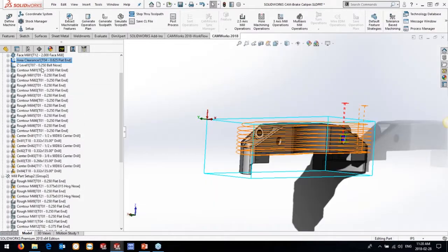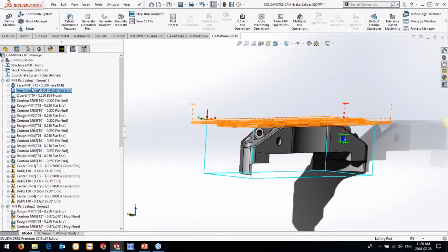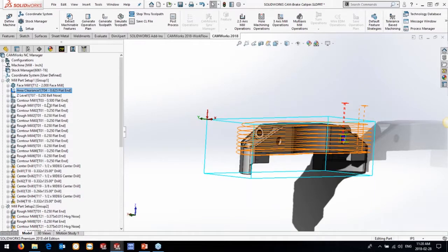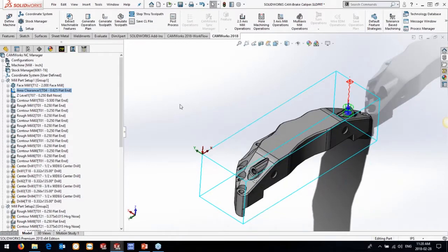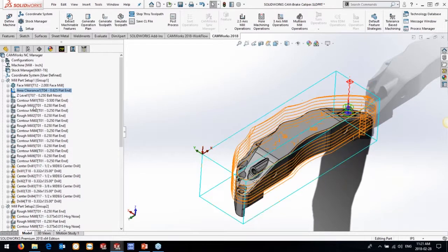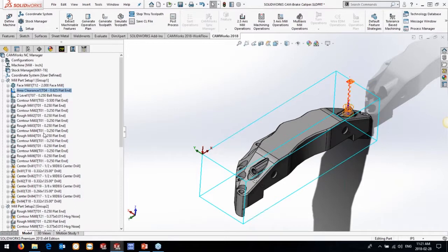And as far as the tool selections go, the software will memorize what tools that you use every time you go and program certain types of geometry. Or you can intelligently link it, triggered off the width of the geometry or the length of the geometry. Say, hey, take the width times it by a value, take the width times it by a higher value, and create a range for a particular tool that you can put in that particular geometry. So that's basically in CAM Standard.